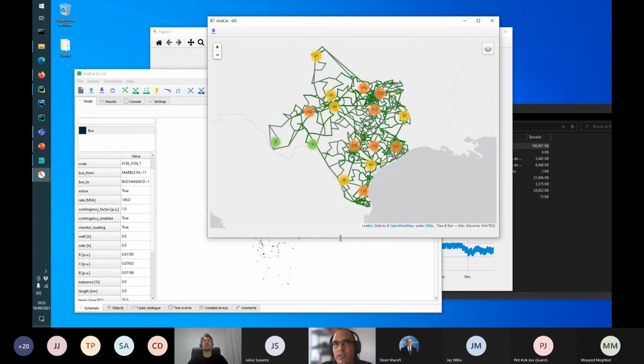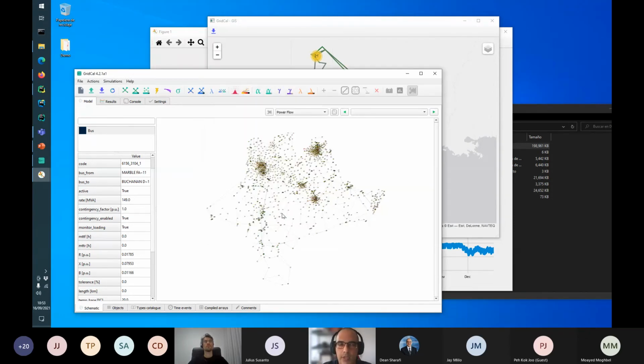Yes. Basically, yeah, okay. Not off the shelf, for sure, but that's something we did. One of the companies had a functionality that we needed. So a real-time simulation. Let's see. So you get a sampling, let's say every 10 seconds or something, and then run the power flow and check, run the power flow and check all the time. So it's actually quite easy. It's a for loop, and then running the power flow inside the for loop and assigning the injections. So that could be a very good starting point, because it's quite simple in principle.